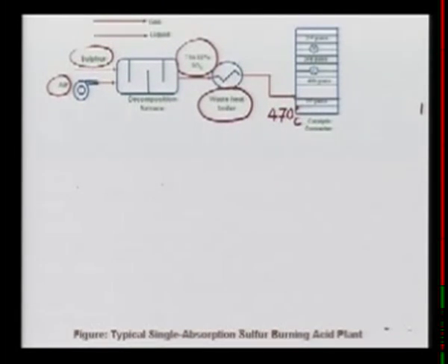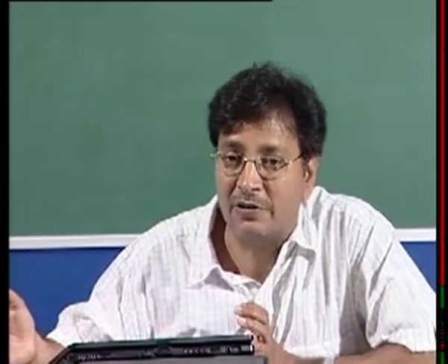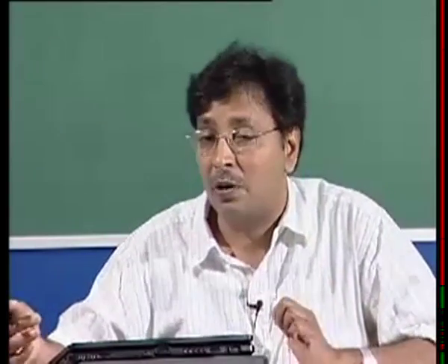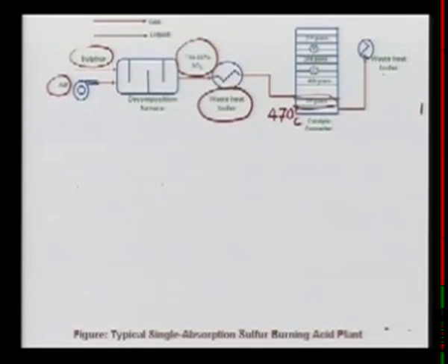So you see here the first pass. This SO2 is the first pass. First pass means it is immediately converted to SO3, and then immediately, once the conversion is done, before it can go back to sulfur dioxide, because remember that it can go back to sulfur dioxide, we quickly recover the heat. So once heat is recovered from the right hand side of the equation, if you recall, there is no possibility of the converted SO3 going back to SO2, but there is still some remaining SO2. So we will again convert the remaining SO2 in various passes.